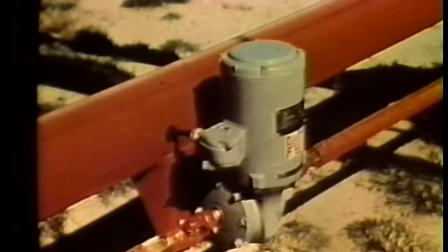Electrically driven center pivot irrigation systems have an electric motor on each tower. The electric motor drives each tower individually through a system of gears and chain or shaft drives. If one tower gets ahead of the others, an electrical switch is tripped which stops the motor. If the tower lags behind, another switch is tripped which restarts the motor. The speed of an electrically driven system is regulated by a control panel located at the pivot point.